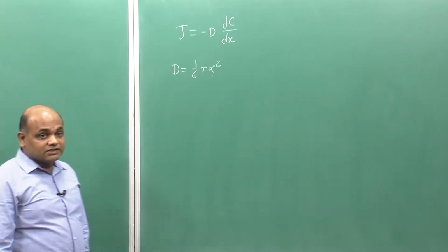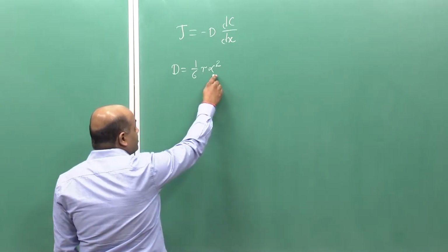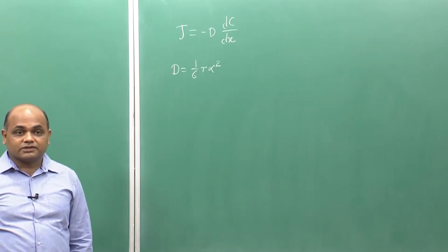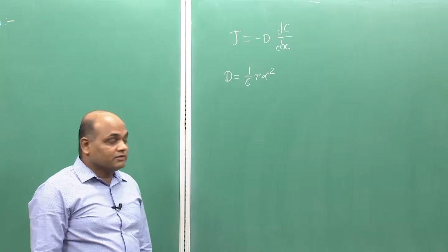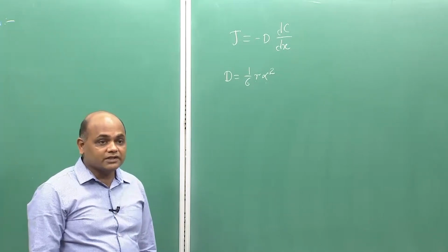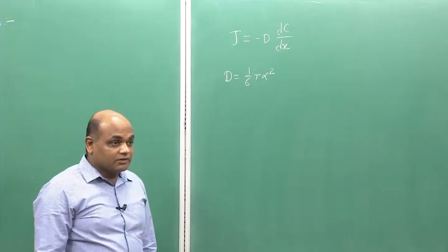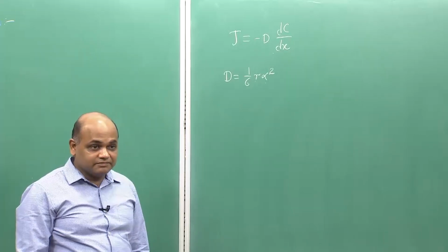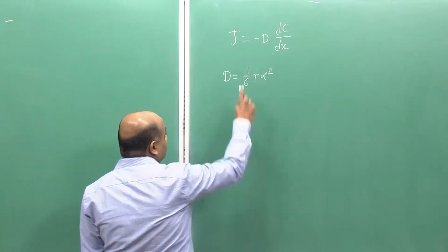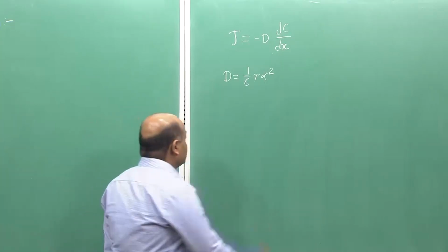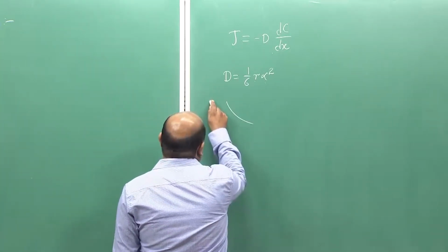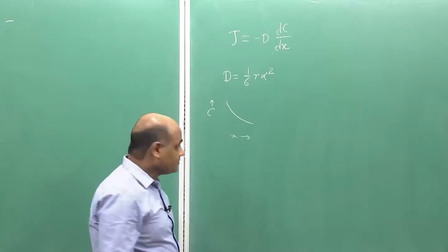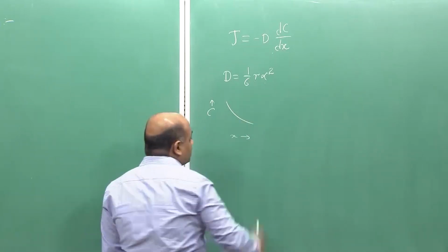If the composition changes, both gamma and alpha would change, right. So d is a function of composition. So only when we have a dilute solution or small concentration gradient, you have d constant and you can use this expression. But if the concentration gradient is larger, then we know that d has to vary with composition, because in the concentration gradient C varies as a function of x. So obviously d will also vary with x.